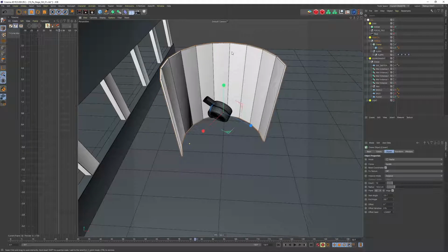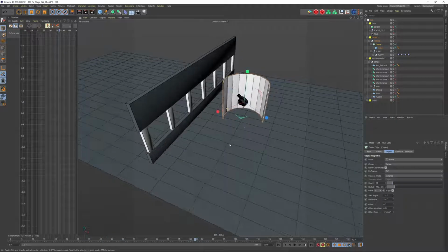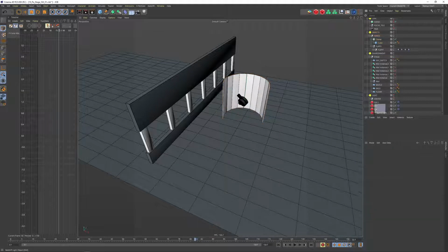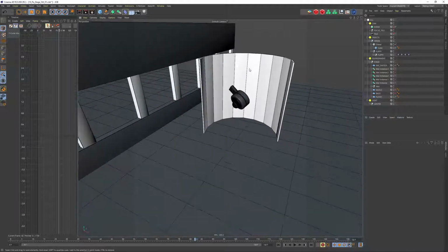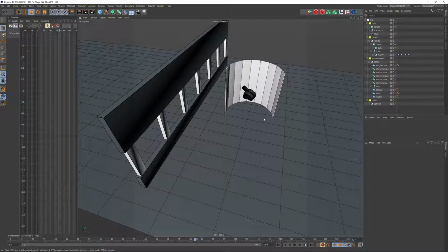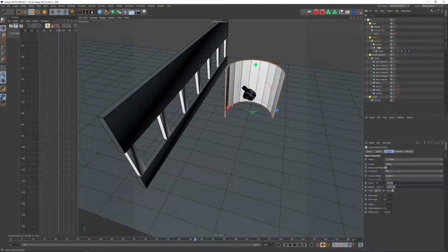The thing is, I want to add a reflection to show you the ray switch later on. If I'm now in my camera, we will have the reflection from these cubes, so I will have to build something around where it can reflect. Otherwise, everything will just reflect from the HDR, which we'll put in later. So again, I'm deleting the Redshift stuff here, so you can put in whatever you want. Therefore, we will need to work on our reflection, and I know that we need to build a place around this. It doesn't have to be really realistic or very good, because I also want to increase depth of field later on, so the reflection won't be that sharp.